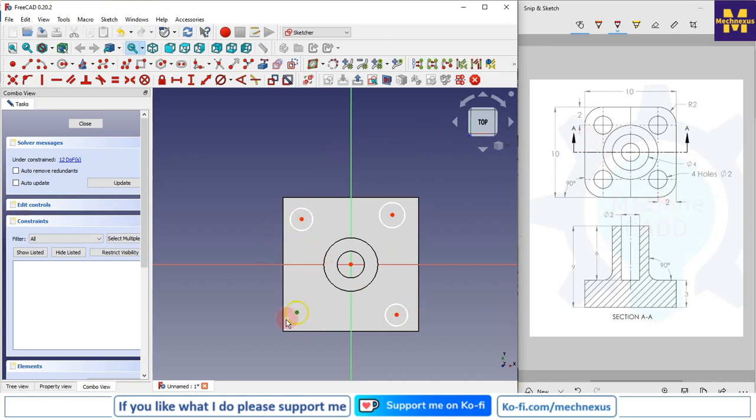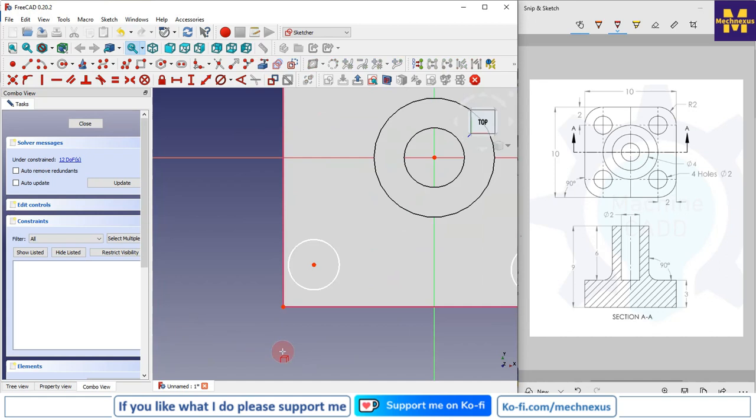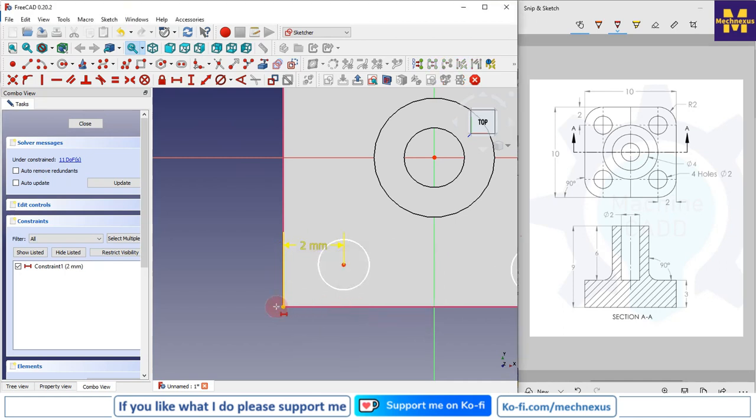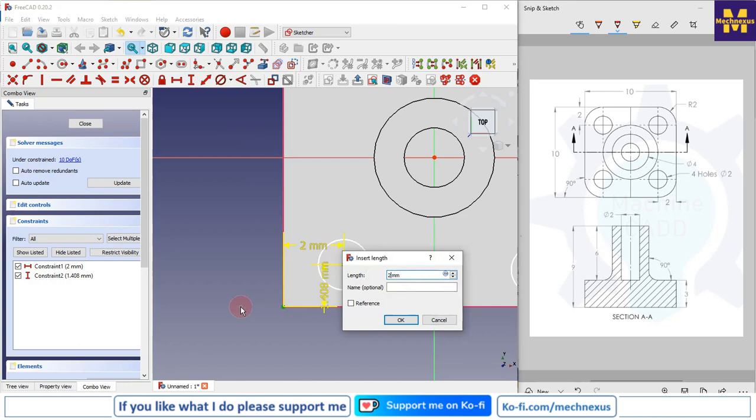For this I will click on convert entities and convert these 2 edges, and then I will select the horizontal dimension, select these 2, and give 2 mm. I will select this one vertical dimension and give 2 mm.